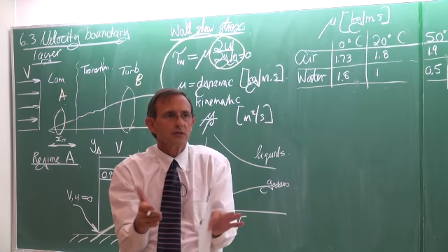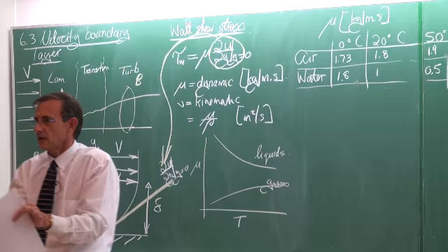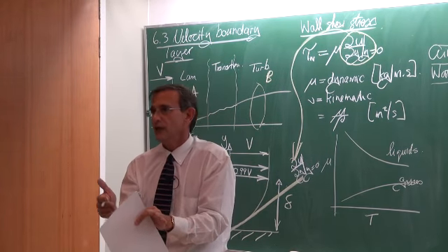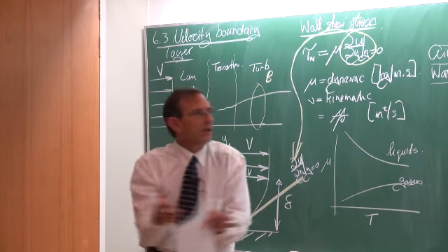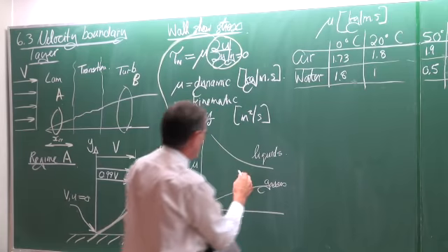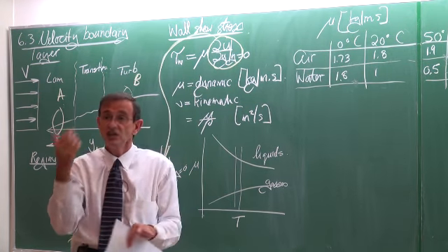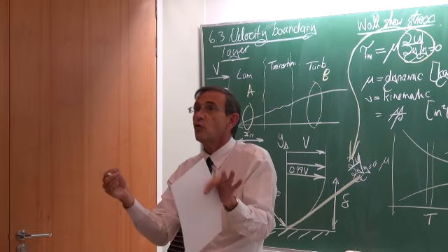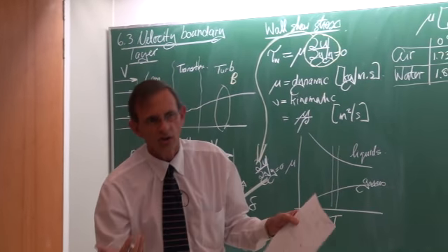Normally the temperature differences that we work with in heat transfer are very seldom in hundreds, maybe orders of tens, and therefore, if you look at those delta T's, you will actually see that the changes in viscosities, in most cases or for many practical problems, are actually for all practical purposes constant.